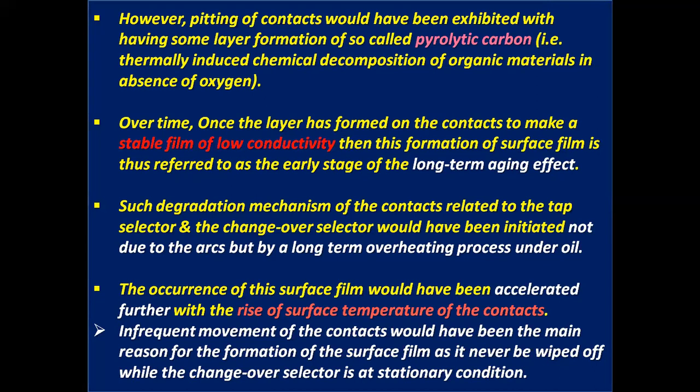Again, I repeat, such degradation mechanism would have been initiated not due to the arcs but by a long-term overheating process under oil. The occurrence of this surface film would have been accelerated further with the rise of surface temperature of the contacts.